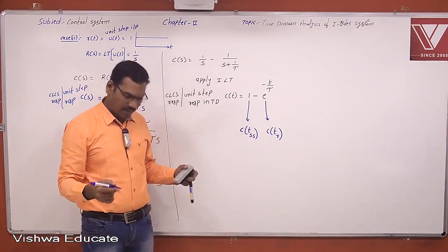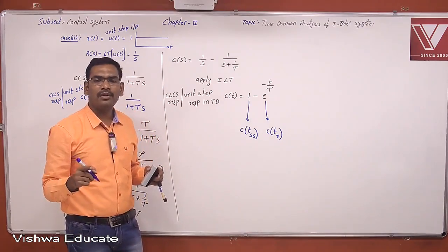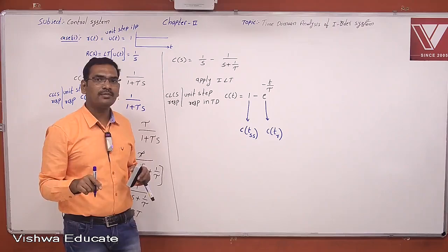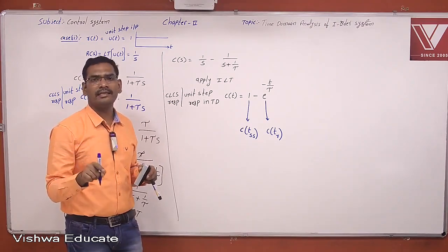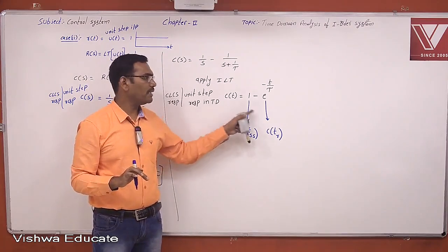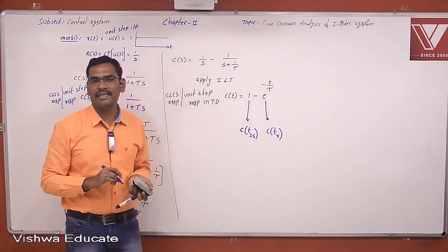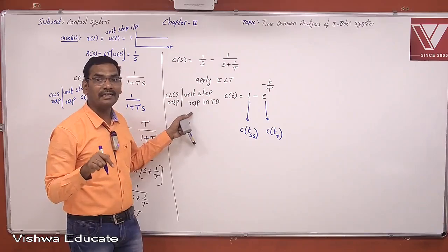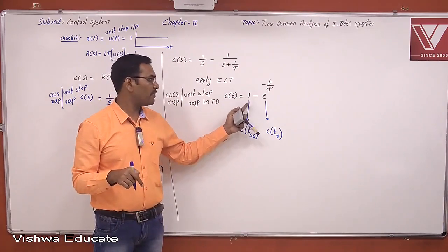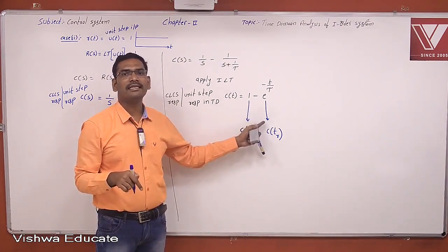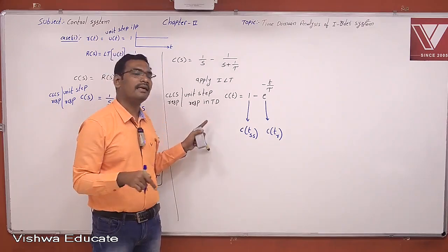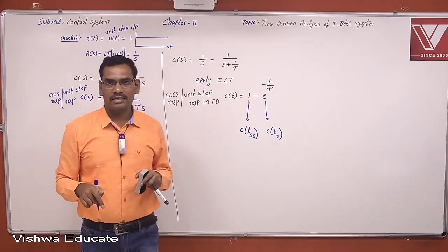But previously, in the case of the impulse response, the time response consisted only of the transient term. There is no steady state term in the impulse response, so there is no steady state analysis. But this is the practical response. This is the reference level. Therefore, this response has both the transient term as well as the steady state term. Therefore, you have a complete time domain analysis in the case of the unit step response, or step response, students.